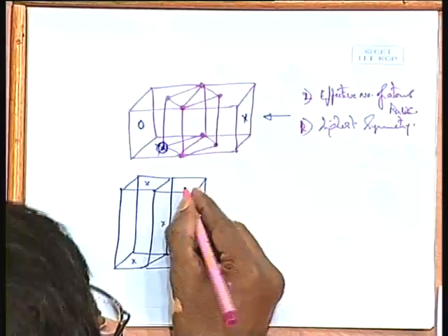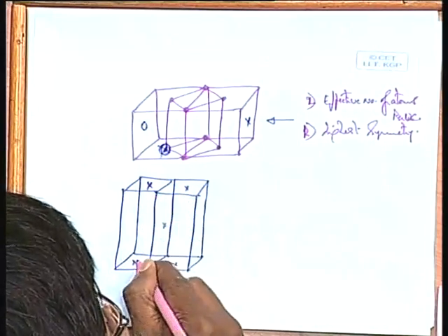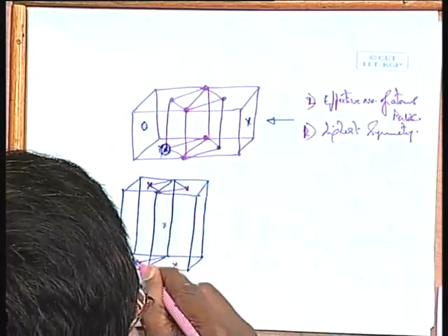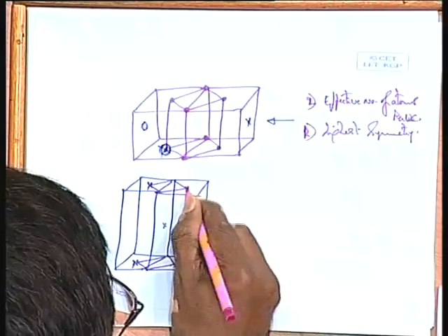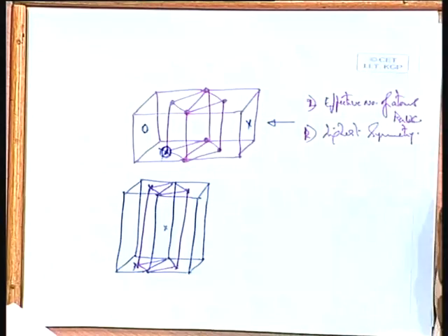Now, that previous logic that we used for base centered cubic, if we extend it to the base centered tetragonal and try to see why base centered tetragonal is not possible, you will see clearly that the moment I take any 2 base centers like this and join them, base centered tetragonal has turned out to be a simple tetragonal.